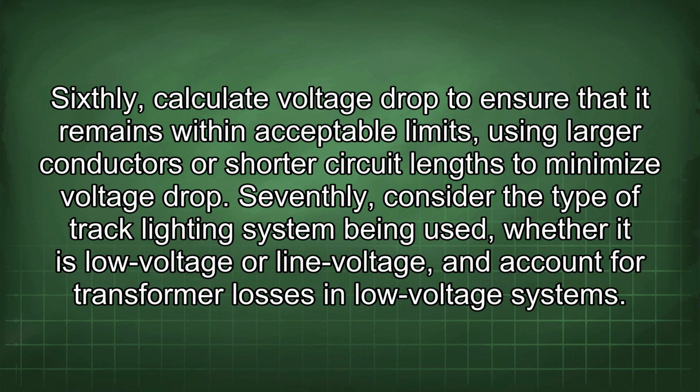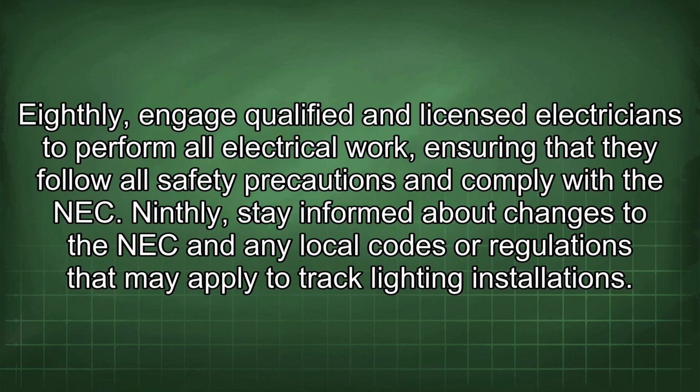Seventhly, consider the type of track lighting system being used, whether it is low voltage or line voltage, and account for transformer losses in low voltage systems. Eighthly, engage qualified and licensed electricians to perform all electrical work, ensuring that they follow all safety precautions and comply with the NEC. Ninthly, stay informed about changes to the NEC and any local codes or regulations that may apply